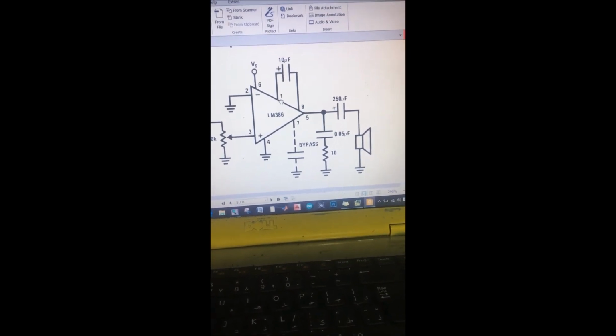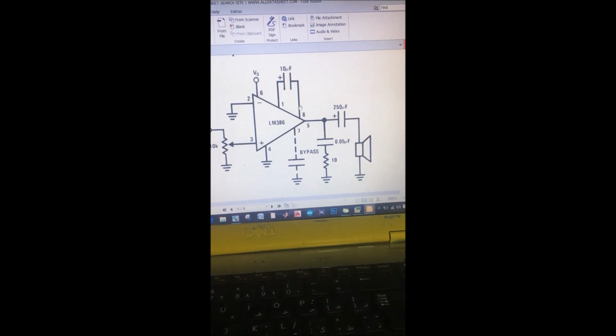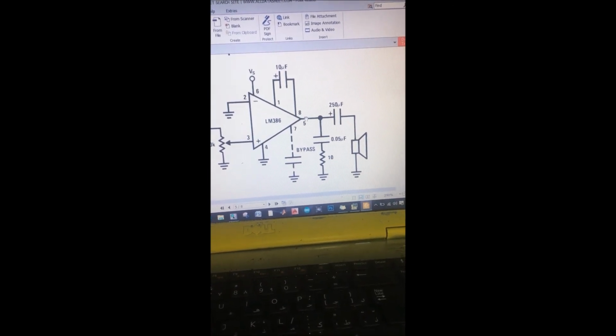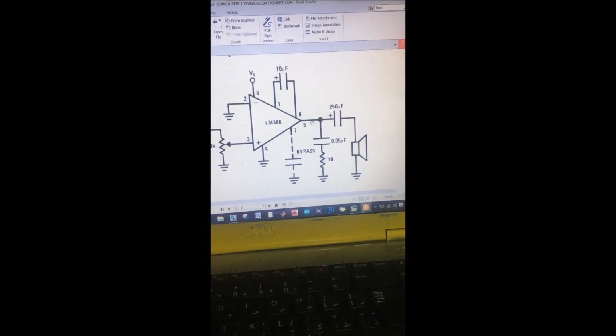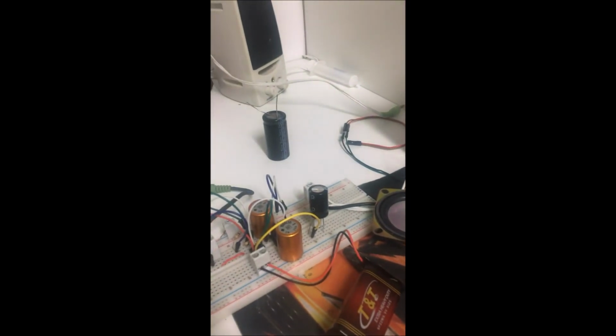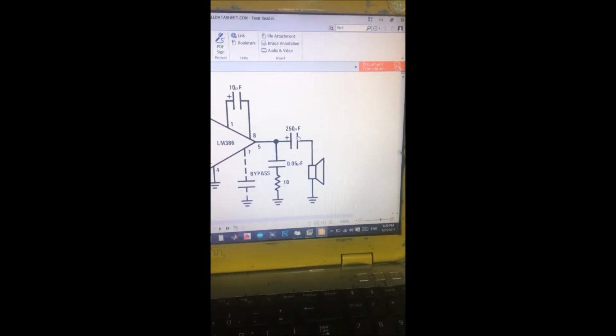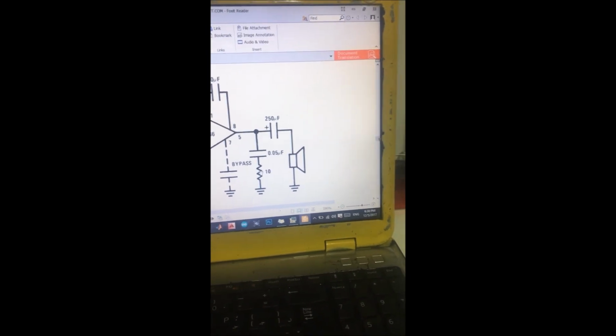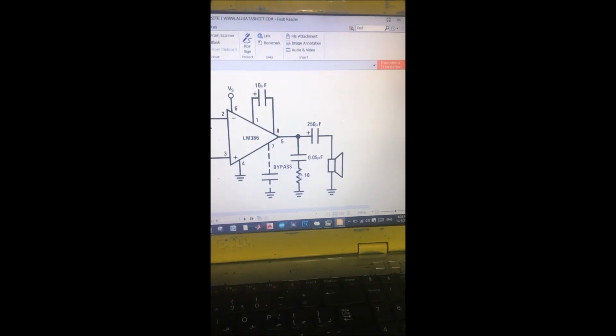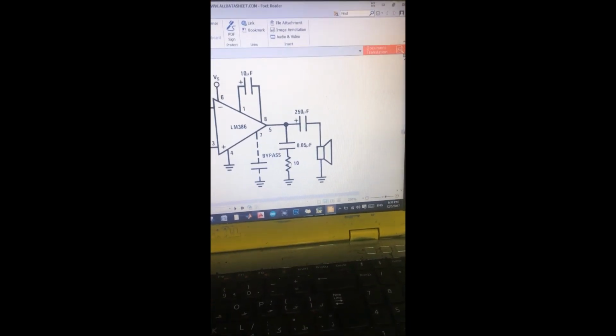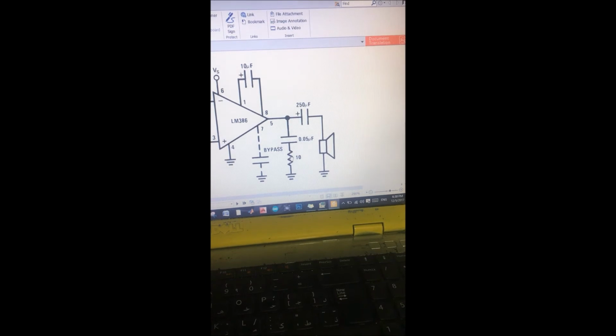We can connect a capacitor from pin 1 to pin 8. Also the output goes to pin 5, but before we connect the speakers, we connect it to a capacitor which reduces the distortion. Also, it's better to use this type of filter, which can reduce all the distortion coming out from the computer, or for frequencies near or higher than 1 kilohertz.